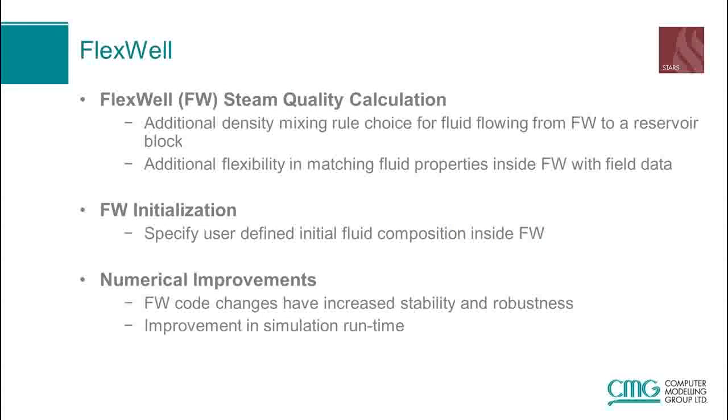Flexwell is our wellbore tool, a fully transient tool that's integrated in STARs. Through a user request, we added an additional density mixing rule for choosing when you have a fluid flowing from the Flexwell to the reservoir block. Now this additional density mixing allows you the flexibility when trying to match properties inside the Flexwell with your actual field data or an analytical analysis.